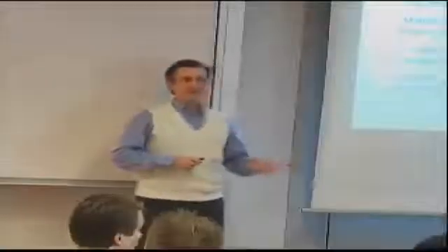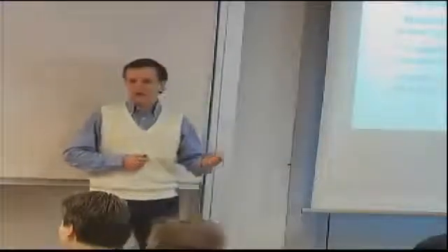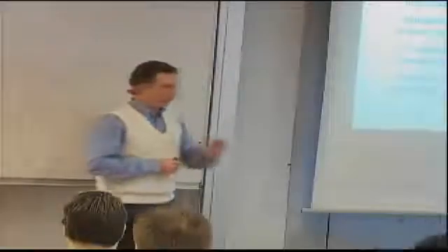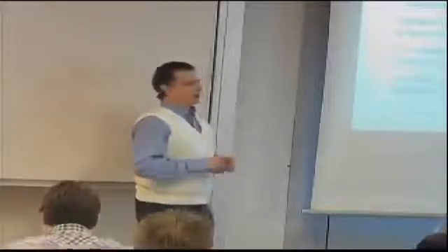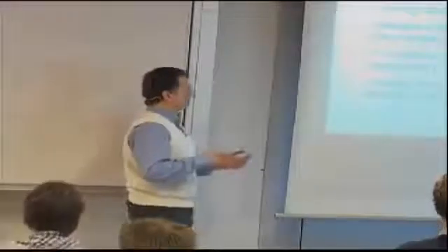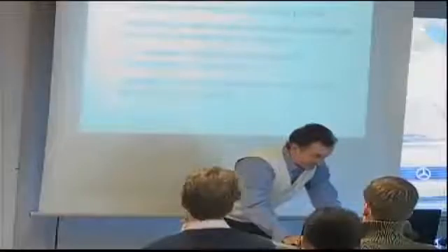And let me say up front that it becomes crucial to know the failure mode for which you are analyzing. If you don't know it, then you might miss it. This finite element code or whatever you are using is tailored to the construction that you made up, and it may not be able to tell you it's going to fail at this specific failure mode, and it might miss it. I'll show you examples throughout the course. Then we'll do the full-blown 17 equations in 17 unknowns for anisotropic elasticity, and we'll try to even start solving those for some relatively simple cases where we can solve them in closed form. So, having said all this as a background,